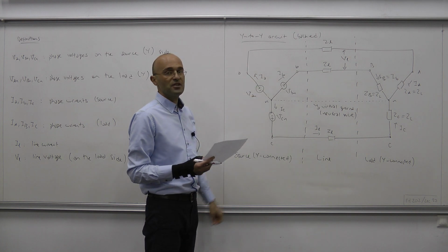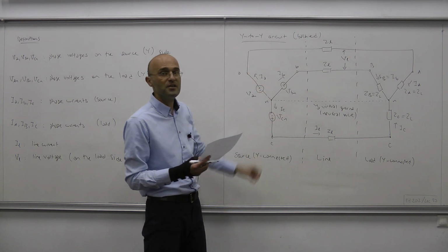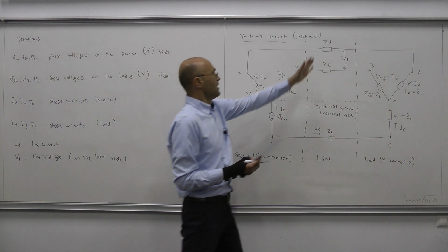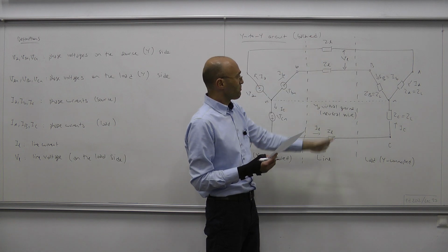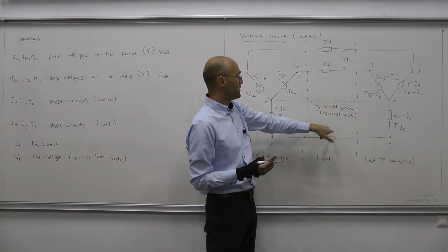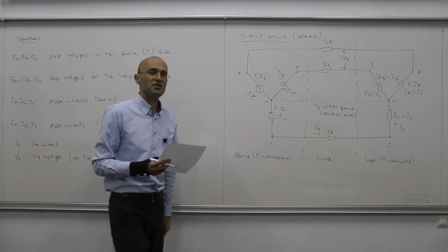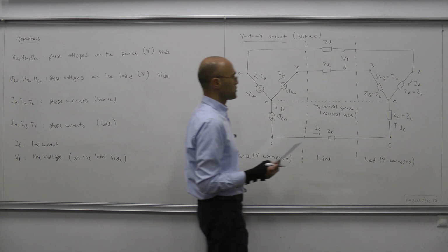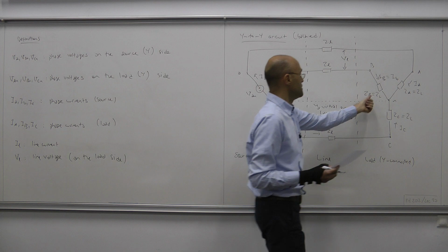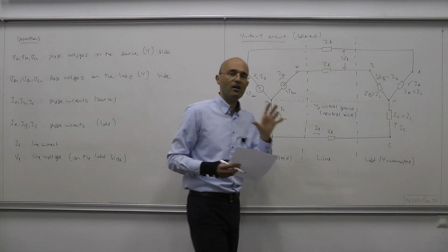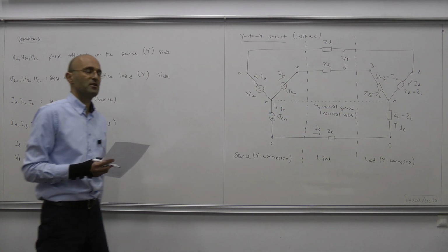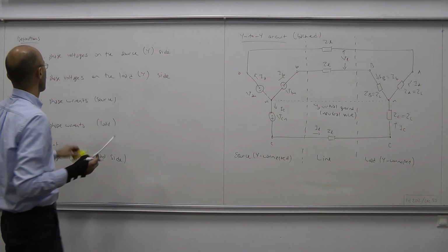That is, they all have equal magnitude and the phase separation is uniform, 120 degrees between any pair. We also mean all the line impedances are equal, which is why we denote them by the same notation, Z sub lowercase l. And balancedness also requires that all the per phase impedances ZA, ZB and ZC are equal, which we denote by Z sub capital L.